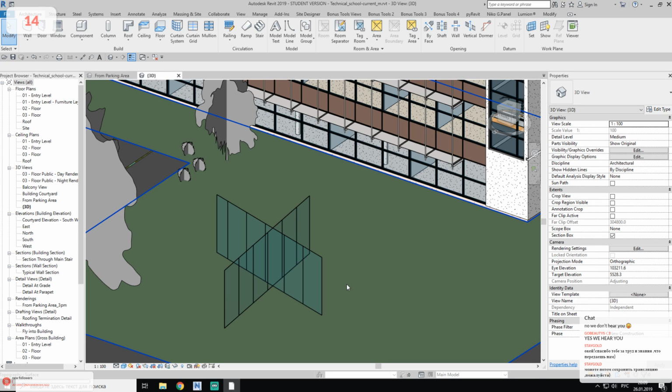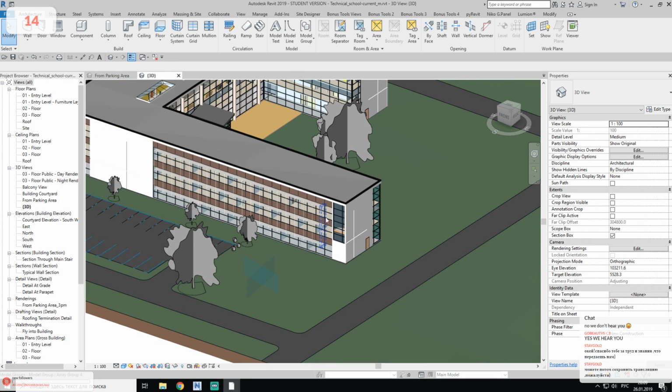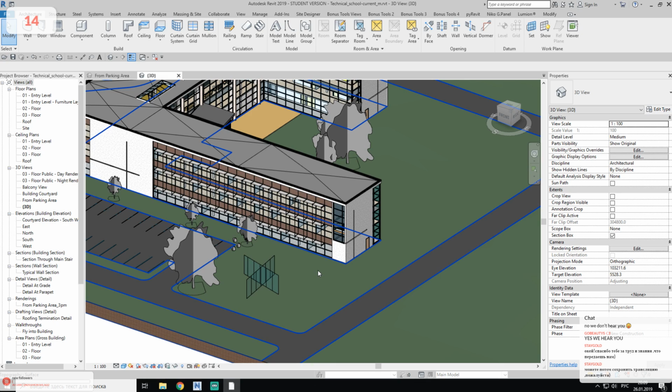So how can you check this? To check this, we are using Navisworks. For a local thing we can use Revit, but let's say you have not a building of 4 levels, you have buildings of maybe 20 levels, and 4 buildings of 20 levels, and for example 20,000 square meters. You cannot change that manually in Revit. That's why you need to use Navisworks.